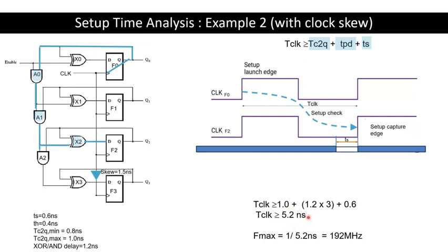So if you have many possible clock periods computed from the same circuit, then we normally take the longest one. Like in this case, we take 5.2 nanoseconds as the best clock, because the clock coming from the worst case will be able to be applied for all the timing paths of the same circuit. Using this to compute the best frequency, we will get 192 megahertz as the frequency to be applied on this circuit.